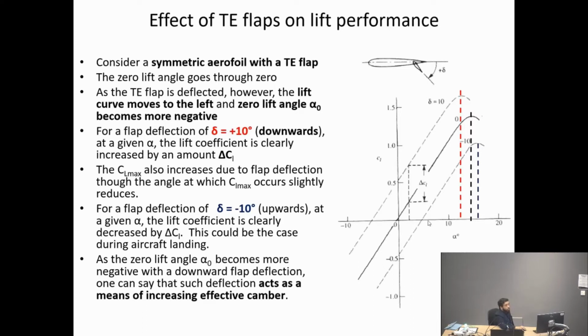Along the whole range of alphas, however, if we look very carefully, it turns out that we are extending the lift, or improving the lift, by using the flaps. However, the stall angle is actually slightly reduced by using the trailing edge flaps for the wing.